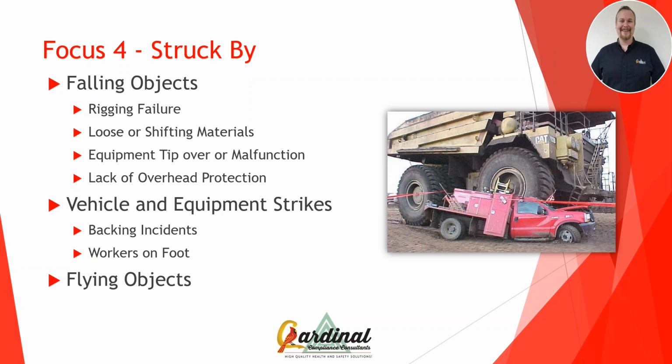They had a pallet, and they had set the piping perpendicular to the slats in the pallet. No type of chocking, nothing to stop them from rolling, and they placed them right next to a toe board, which was about the same height as that pallet, and there was nothing stopping them from rolling. And so these loose materials, when they started rolling, nothing stopped them from dropping 8 stories.